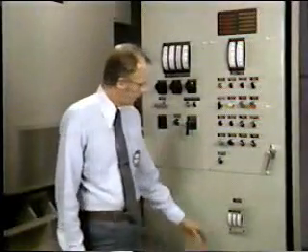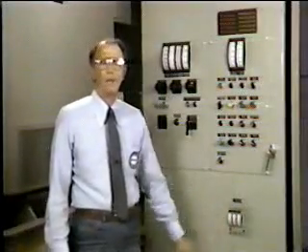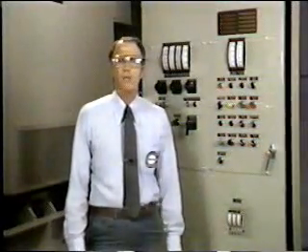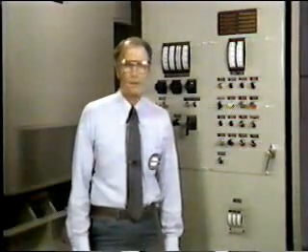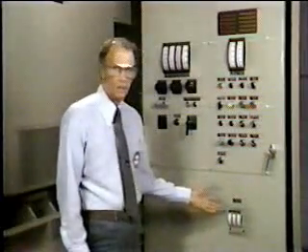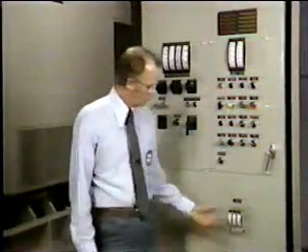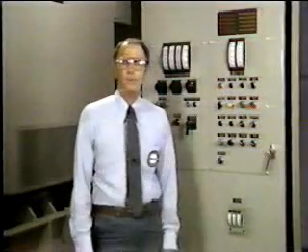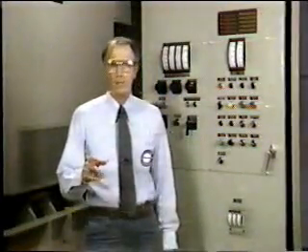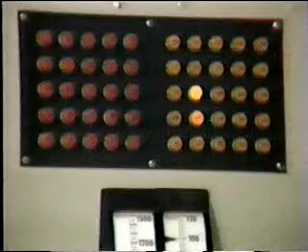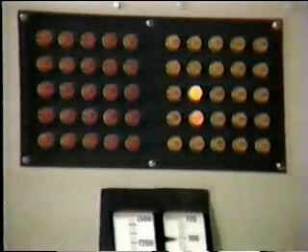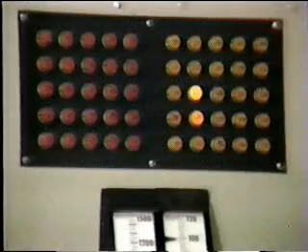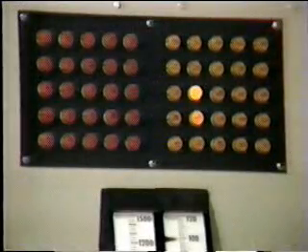The generator winding temperature monitor, Z170, and the generator bearing temperature monitor, Z170-1, are both optional. If your package includes these two monitors, they will be mounted here on the console door. This package includes Z170. Both monitors receive an input from RTDs located in the generator windings or bearings. The first set point of each monitor is a warning that the temperature is approaching the shutdown point. If the temperature continues to rise to the second set point, the monitor will initiate a malfunction shutdown.